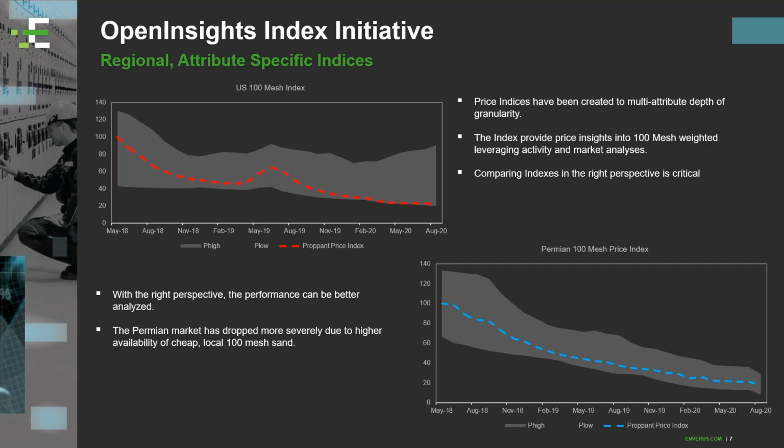And really that goes to two things: A, that influx of in-basin sand, but also the preponderance and tendency to use 100 mesh sand. And I think too, some widening of the mesh distribution of what is 100 mesh. Most of the time people call it 40/70, but we've seen those cuts, due to mine efficiency, be a little bit looser, and people being willing to pump a little bit broader spectrum sand as 100 mesh too. So, a couple of different things at play there.